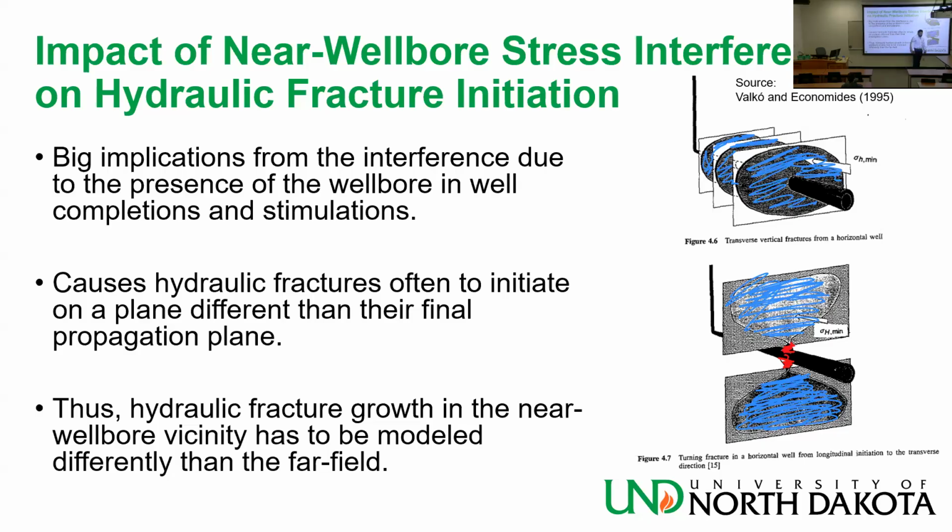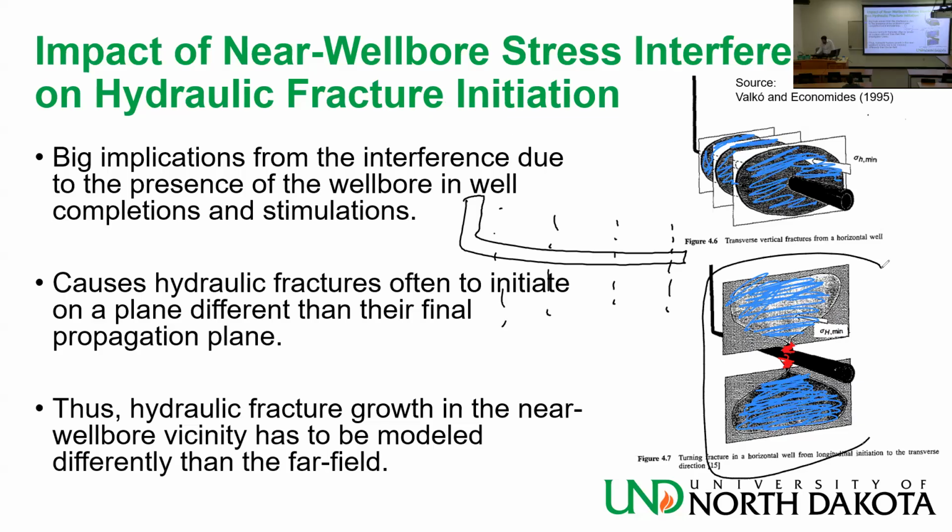Also, remember those longitudinal fracture components, they can go long, okay? They can go long along the wellbore. And remember, you have a well like this, and you try to stimulate it, and you are going to do it in stages. This is the first stage you are going to try to stimulate, and then another stage, and then another stage, and so on and so forth. Now, if I do what I have here, basically I get a transverse fracture far away from the well.